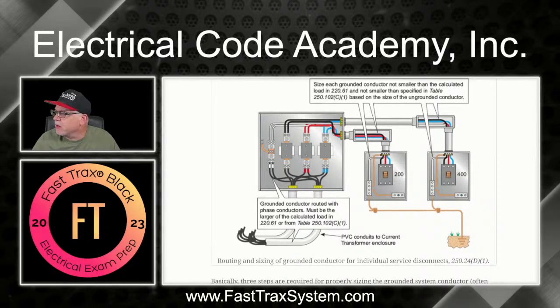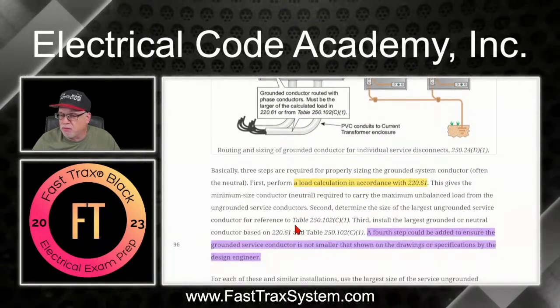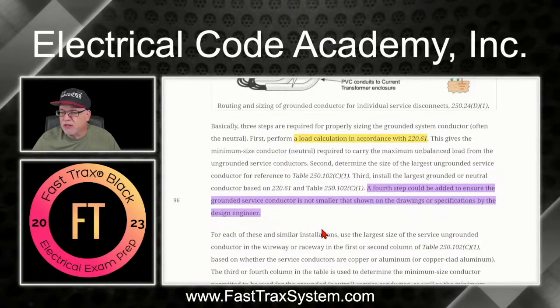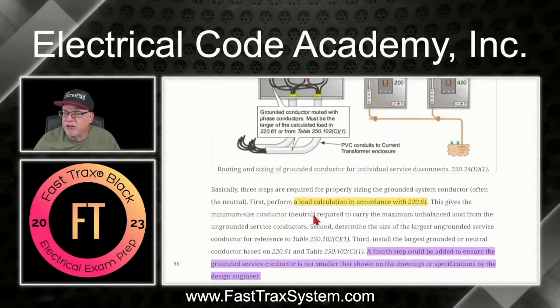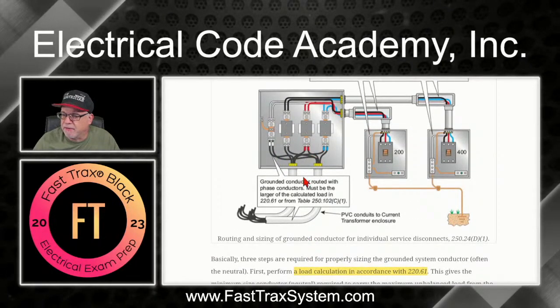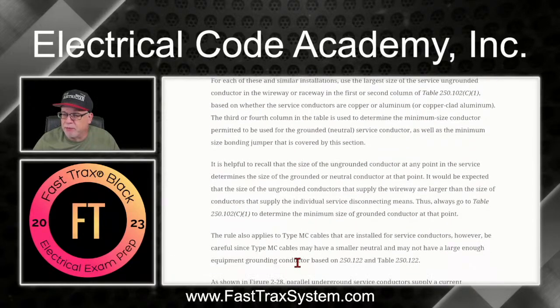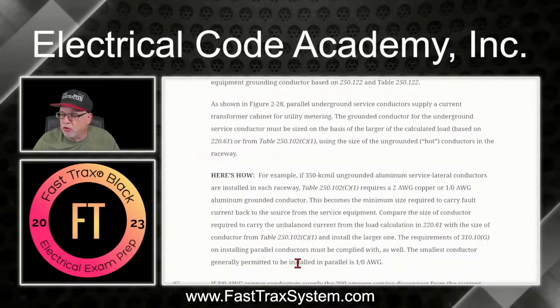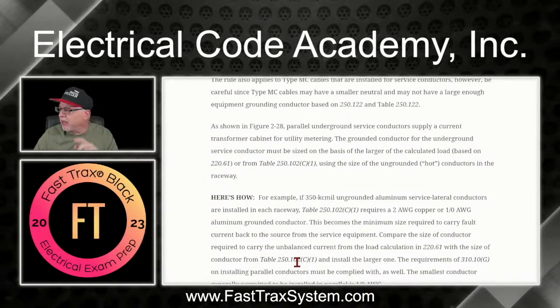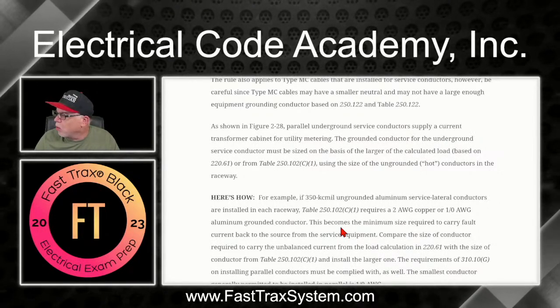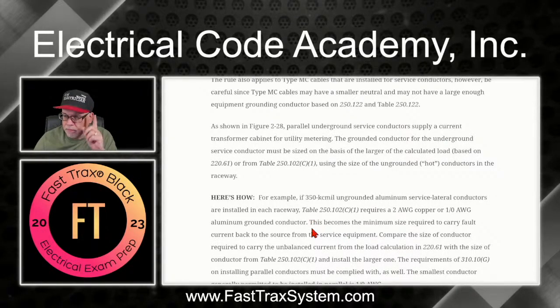Now, that, again, is in for each raceway, but we're going to also remind you of something that is critically important. So that's just base information on how we're running this scenario right here, because I got to remind you of something, right? As we get further into this example, I want to show you an example of why you would say, okay, so that looks like it would just be 2 copper and 1/0 aluminum. All right. Watch now.